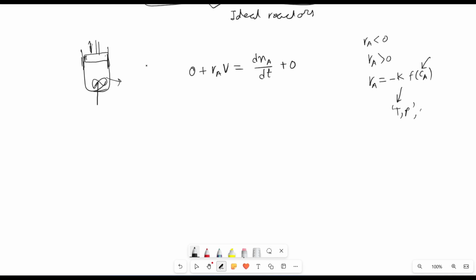So in industry, this gives a rough ballpark that if the reactor is 90% ideal, then we can use the assumption of a batch reactor. Now suppose the volume is fixed, if the entire thing is filled with liquid or gas. This volume is the volume of the reacting species. It may be equal to the reactor volume or may not. It depends.